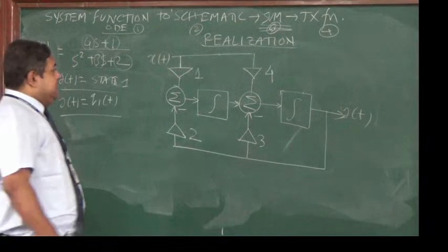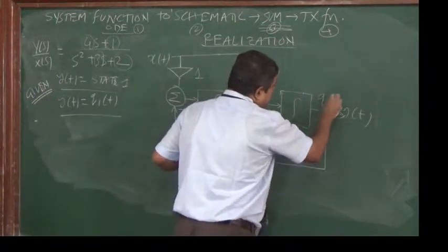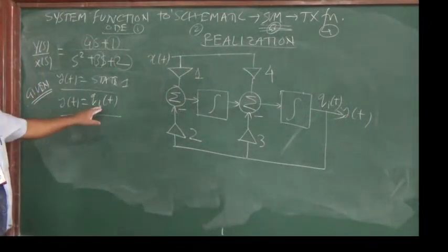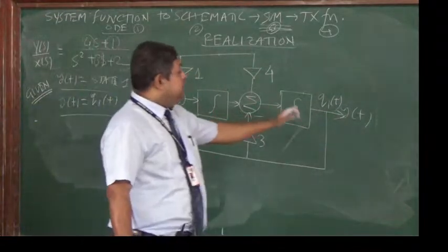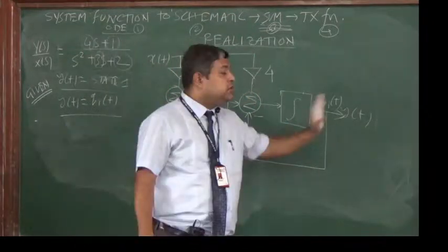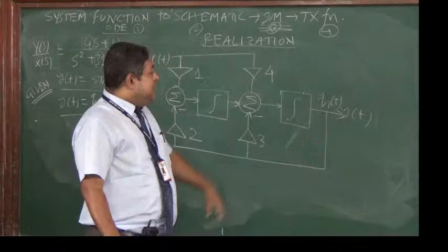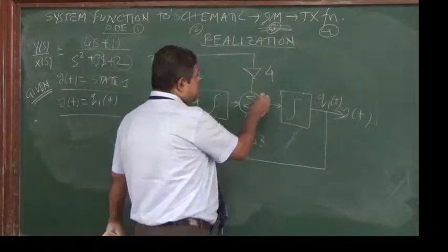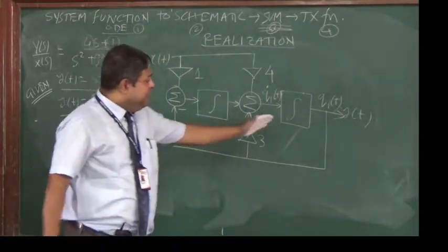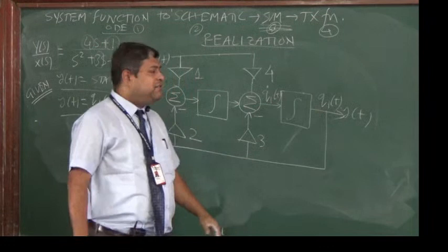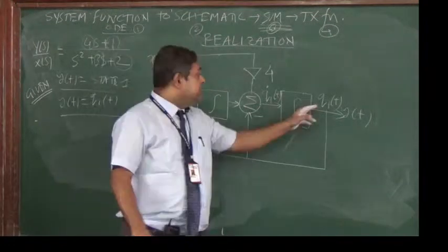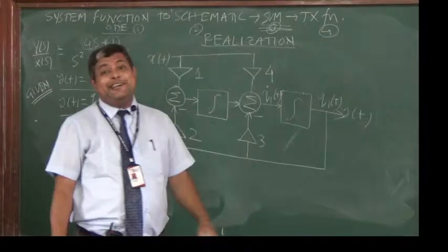Now this thing has to be q1(t). Automatically it comes because the output equation is given: y(t) = q1(t). Whatever is being generated at the output, that same thing is nothing but y(t). So q1(t): some quantity is integrated and we are getting q1(t). So what will this be? This will be q1 dot(t). Integration of differentiation comes to be the same factor. So x1 dot(t) integration comes to be x1(t). Same thing, q1(t) is the integrated output of q1 dot(t).